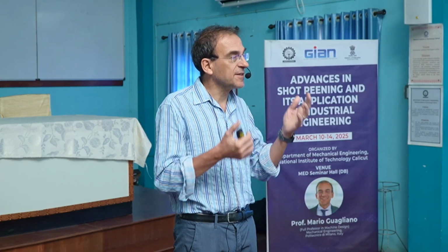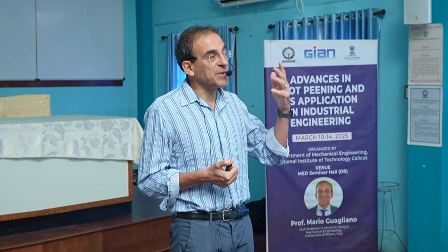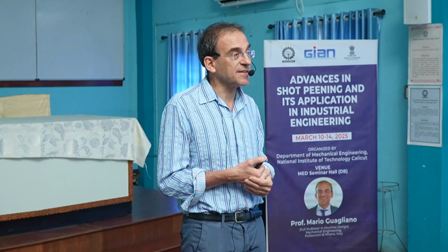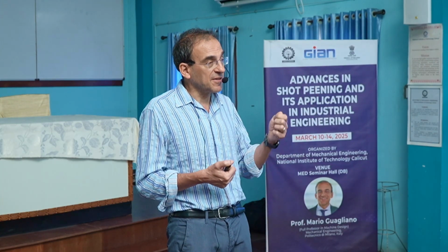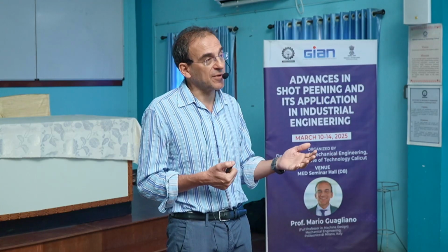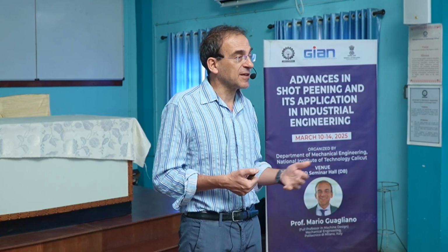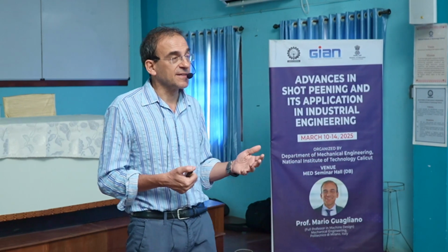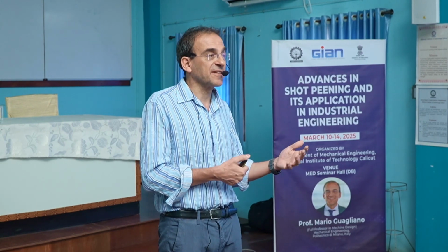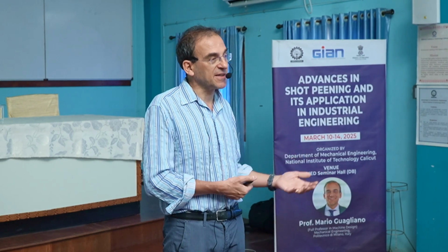And so in this case, shot peening is the last, final treatment, and the gears have been previously carburized or can also be carbonitrided. Anyway, they are surface hardened by thermal or thermochemical treatment.